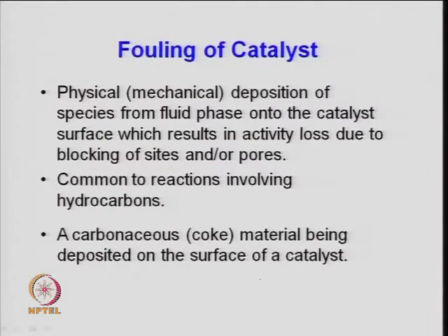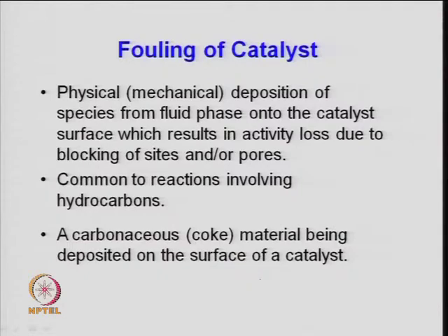So, the first thing is poisoning and the second is fouling. Fouling, as I said, is carbon or dirt: the deposition of carbonaceous material on the surface of a catalyst is known as fouling. It can be physical or mechanical deposition of species from the fluid phase. Sometimes the feedstock may contain coke precursors, like the aromatics I mentioned. If the feed contains more aromatics, then the carbon on the catalyst will be more. So, that is because of the feedstock.